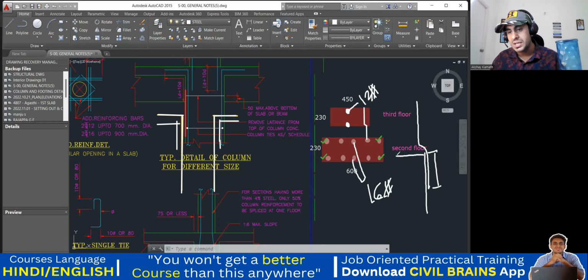It has to be taken like this. So this much development length you are supposed to give. That is LD plus 16 times the diameter of the bar. You can see the same thing here. See, this was your bottom bar. You brought it like this and you stopped it like this. So this will be your development length, and then this will be your lap length.